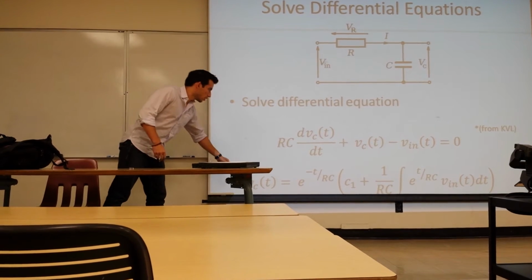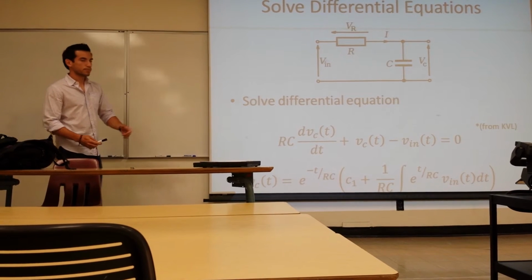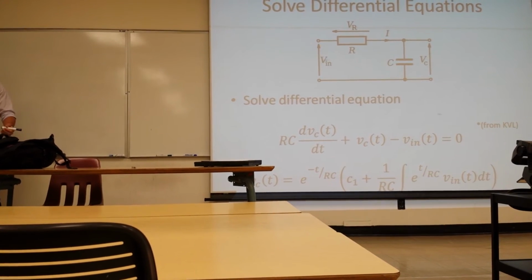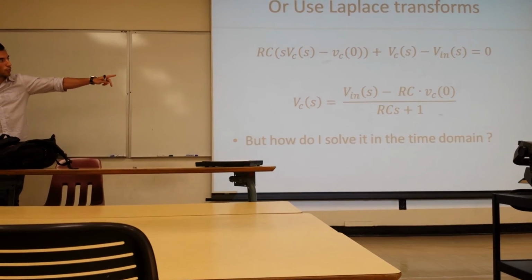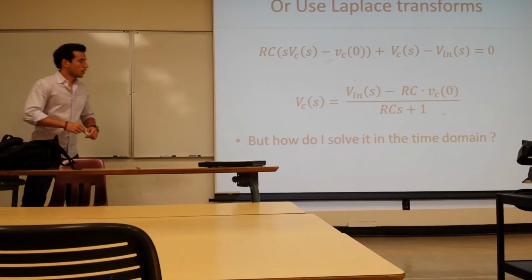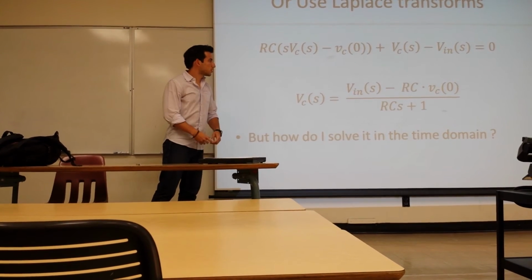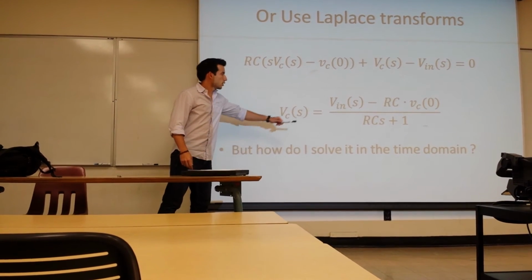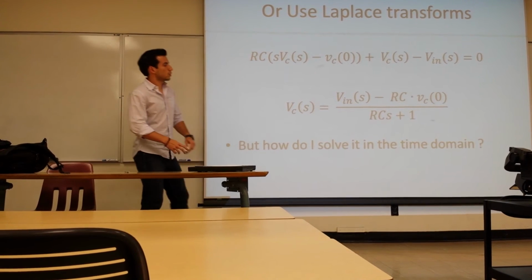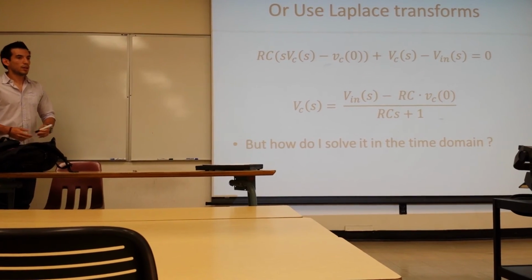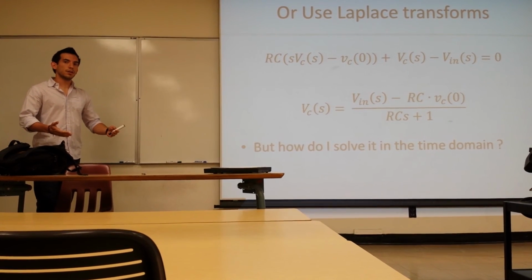And if you want to solve it, this is the approach to solve the equation, but it might be lengthy. So what can we do? We recognize that that's a differential equation and solve it using Laplace transforms. All those integrations and differentiations are just going to turn into multiplications and divisions. And as long as we know our input voltage, we can also take the transform of it, together with the initial conditions.